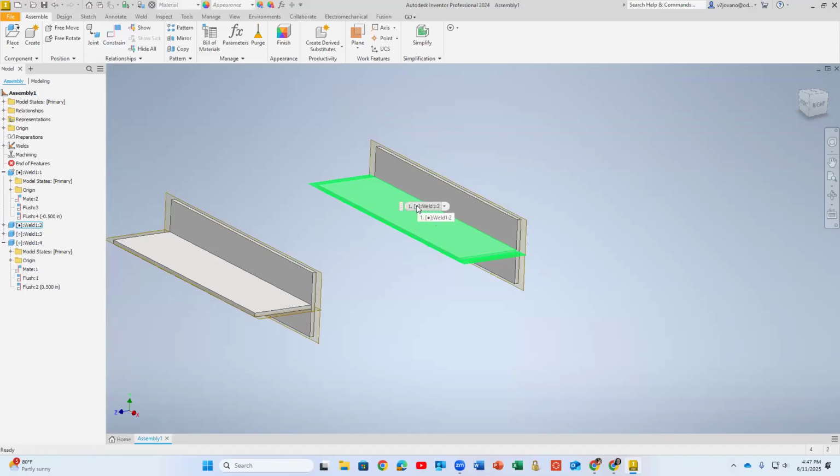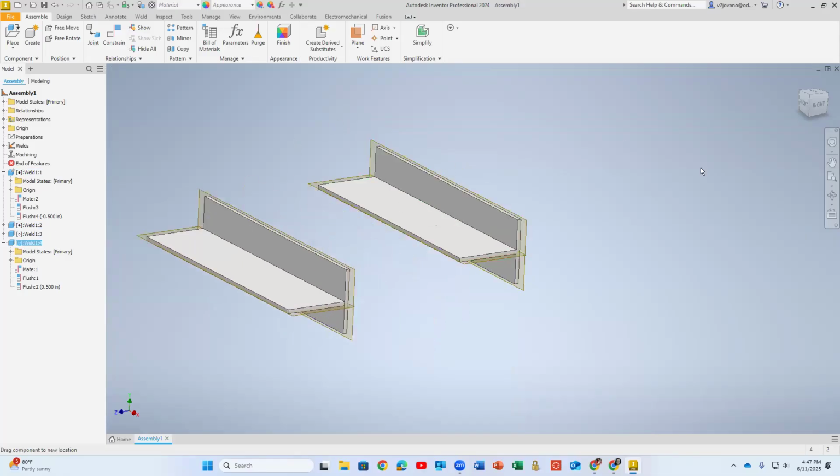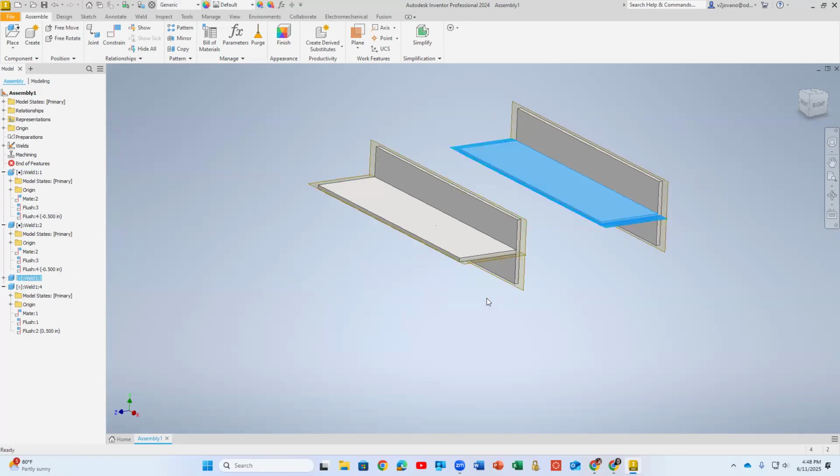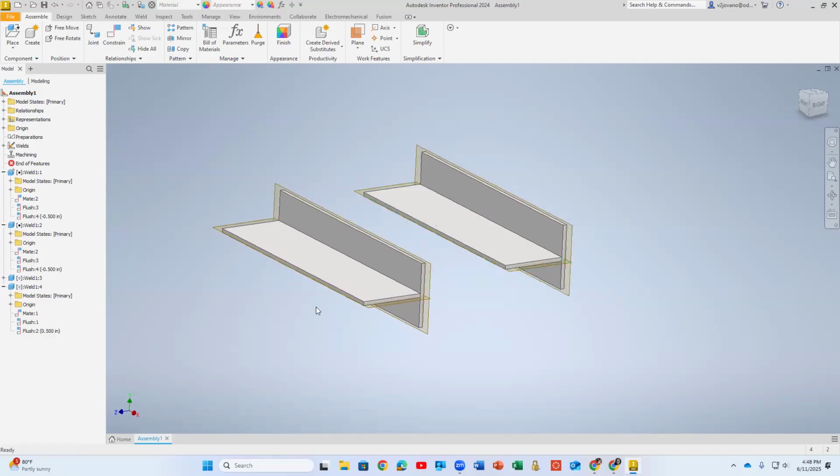So basically, now we have these two, and they're assemblies, but we still can move them. We didn't ground any of them. So this one kind of looks grounded. Let me see. Weld has this mate, has this flush, and this one. Okay, looks good. So let's see what we're doing. In this one, it looks like I can move around. Okay. So they say left click on selected face, assemble them. They're all good.